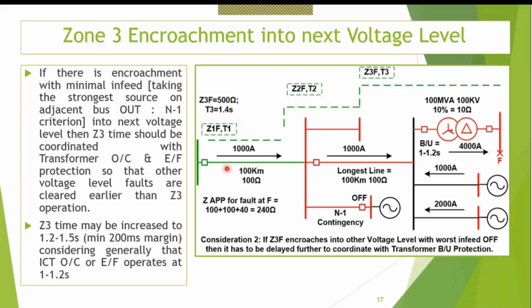Okay, this will operate. I'm repeating just once more. I have a fault over here. This 10 ohm impedance is being helped by the infeed over here. This impedance is increasing due to fault infeed from the remote bus terminals, but then also this relay will operate.